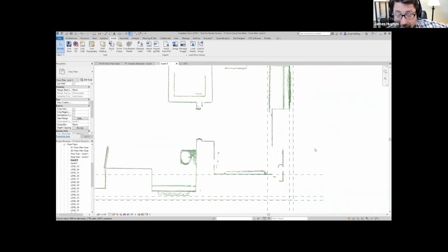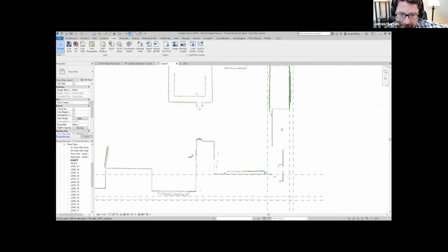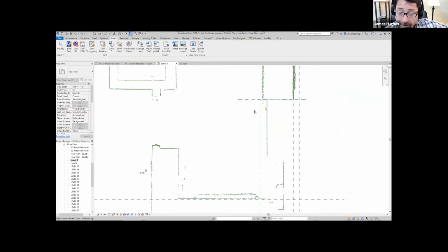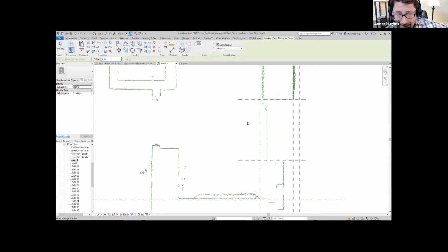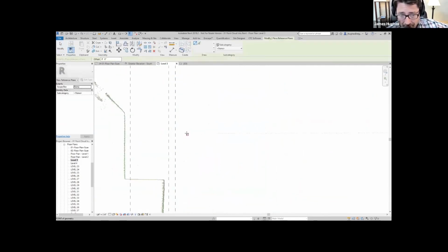I just limited the depth of the point cloud scan. So you're not seeing the points on the floor anymore. You see a 6-inch ribbon. If I change this to 310, now you get a little 2-inch ribbon of point cloud dots, and that lets you very precisely place reference planes and then later walls and windows and other elements. And so the key to working with point cloud scans is to limit the depth of your view, whether that's a plan view like this or a section view.